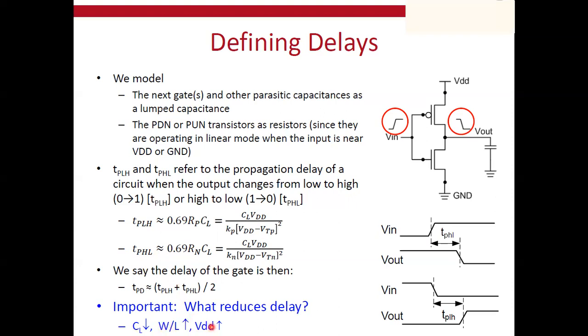However, you can see that this proportionality is somehow against technology, because usually whenever we go into technology, we are seeking a lower VDD and a lower W/L ratio. That's why theoretically you can reduce the capacitance value, but when it comes to technology, it is not so easy to reduce the capacitance value.